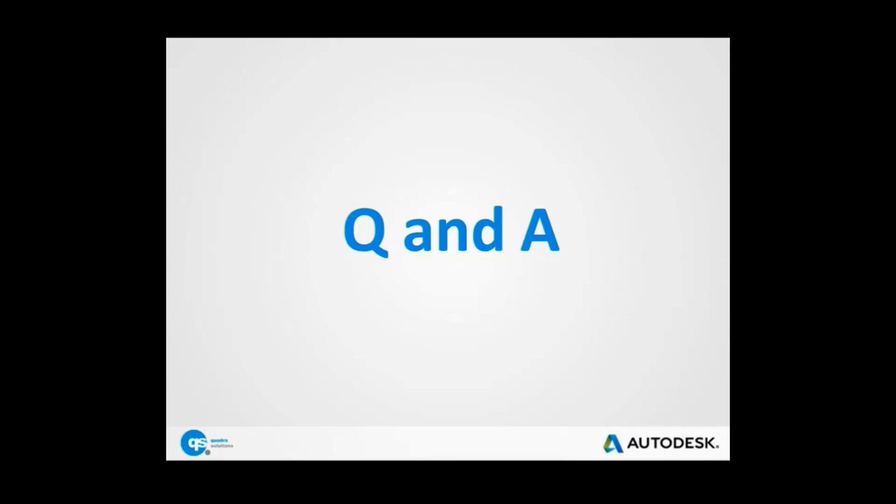Version requirements on Inventor. Sorry, I'll read the question. What are the version requirements on Inventor to be able to use Nastran in CAD? Right, it'll be year for year. So if you have 2015 Inventor, you'll need 2015 Nastran. If you go for 2016 Inventor, you'll need 2016 Nastran. Right, so the two versions need to be aligned. Right, okay. Question here, looking through: is there a 32-bit available for download? No, it's all 64-bit. Okay, so not really releasing 32-bit then.